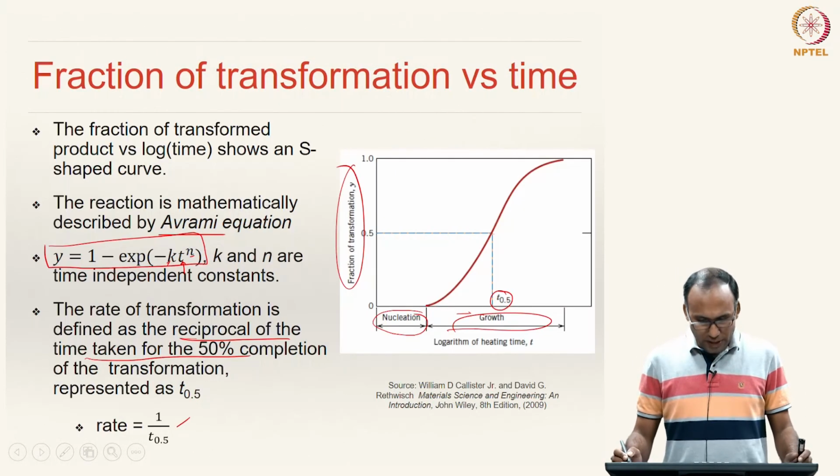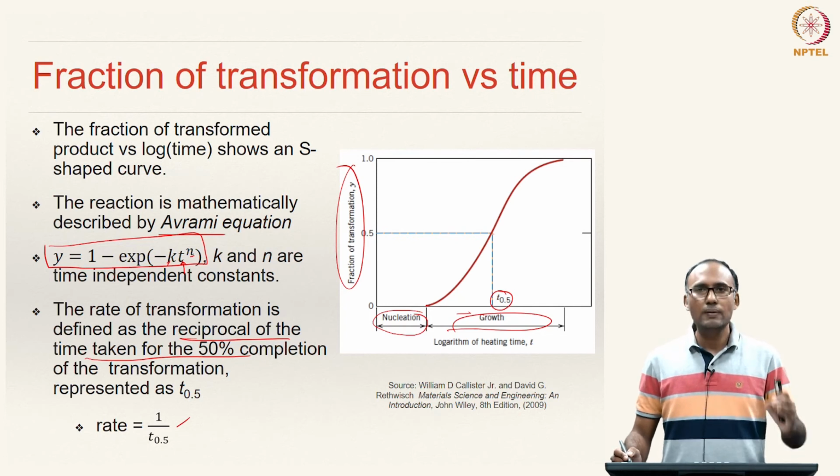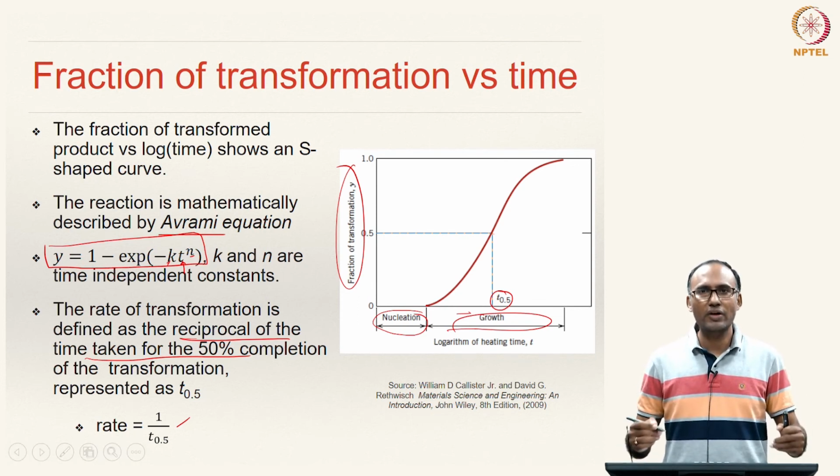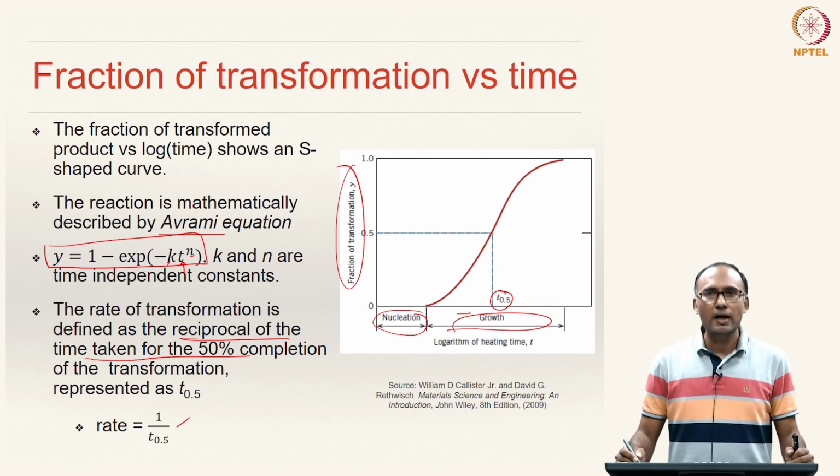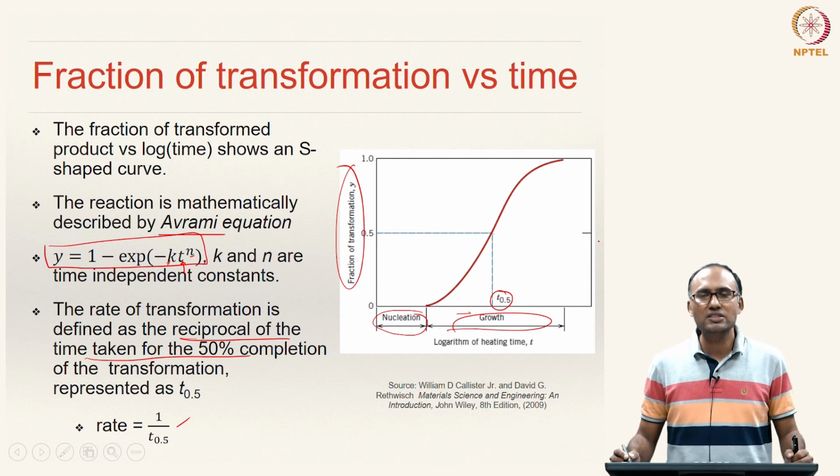All right. So, with that we have understood how nucleation happens under different conditions, homogeneous and heterogeneous nucleation, and then we have discussed the concept of activation free energy and critical radius R star, and how activation free energy changes as a function of temperature.